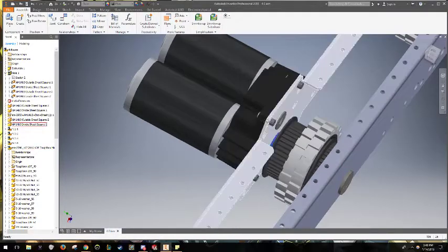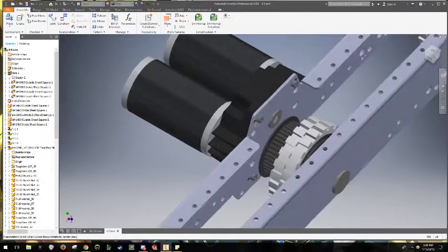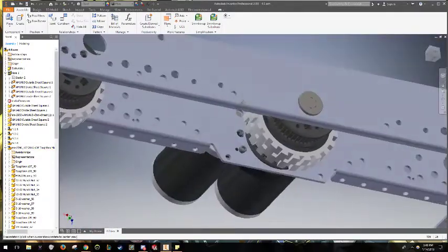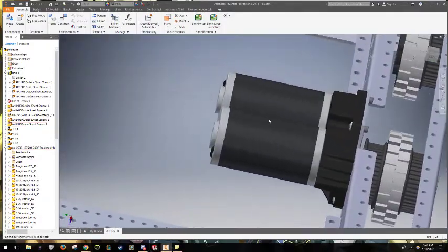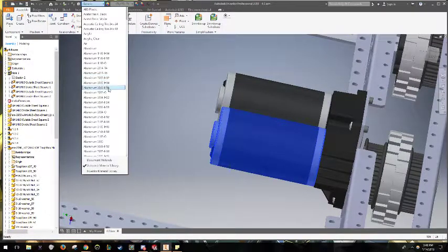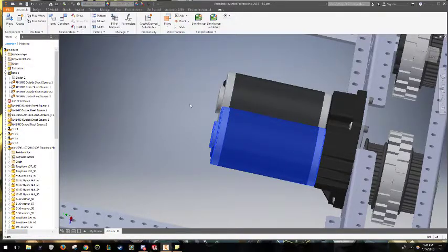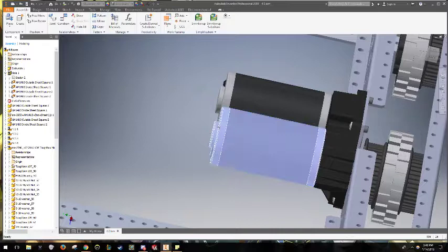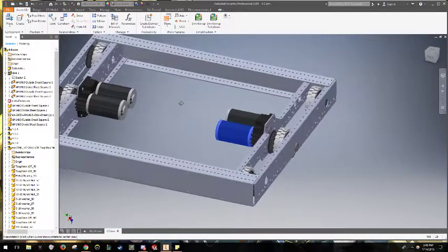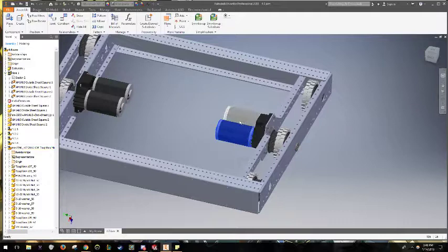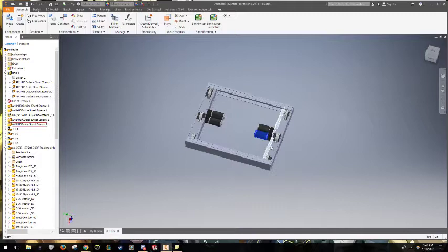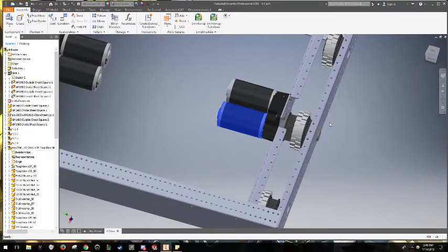And we don't need to do the weights of small stuff like these bolts and these nuts here. That's pretty pointless. I don't really think it helps to accurately model the weight of the object. So these aren't actually aluminum 6061, but the closest density material to what's inside these sim motors is aluminum 6061. So we're just going to go with that for our purposes. Always save, constantly save. You don't want to lose your progress.